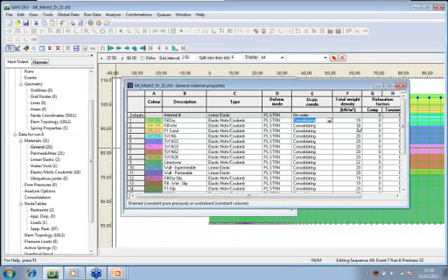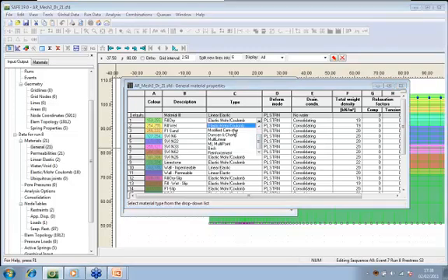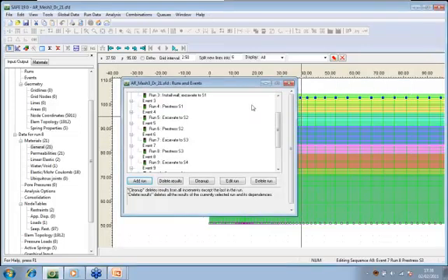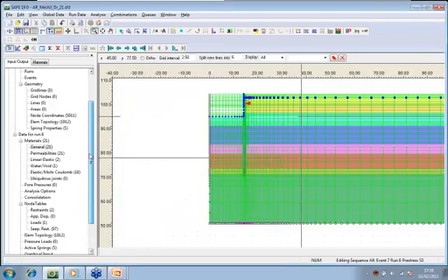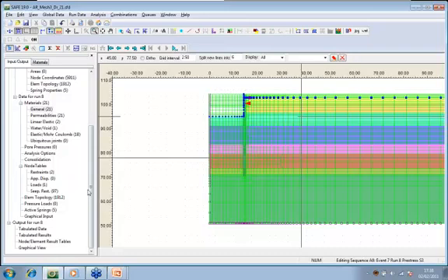So we've got different problems there. I can specify properties for my soil. As I previously mentioned, elastic Mohr-Coulomb is popular, but we've also got brick, modified Cam-clay, Duncan and Chang. So there are a number of different types of models here that we could use for the materials. That'll just give you a quick demonstration of the inputs and how that works.